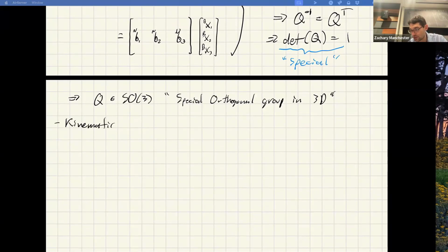And what that really refers to is how do I integrate velocities into rotation? So if I have an omega, in other words, if I have a gyro, if I give you Q naught, the initial conditions, and I give you a perfect gyro on your thing that's wiggling around, how do I integrate omega to get Q of t? If I give you Q naught and omega of t and it's perfect, how do I take that time history of omegas and the initial Q and give you Q of t for all time?